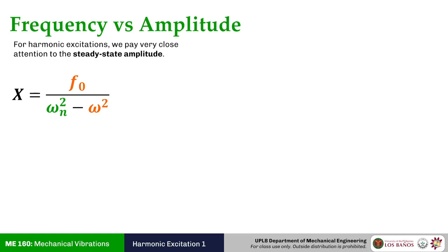Instead of interpreting everything with respect to time, we're going to interpret amplitude with respect to frequency. So the natural frequency again is a system property. Your forcing frequency is something that's contributed by the disturbance. What's the difference? The system property can't easily be changed, but the forcing frequency you can potentially adjust. So this is the more adjustable of the frequencies.